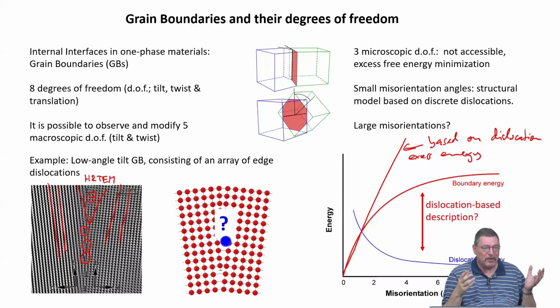But in principle, you have to assume that twin boundaries do affect a lot how dislocations transmit through a grain and through that boundary or not, because they are really obstacles. But in terms of stored excess energy in your material, you can count the twin boundaries out because they contribute only very little.